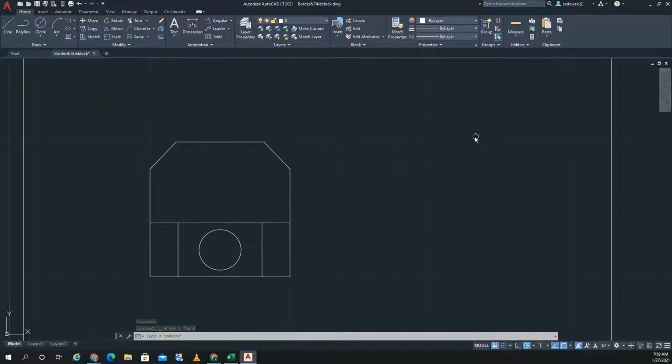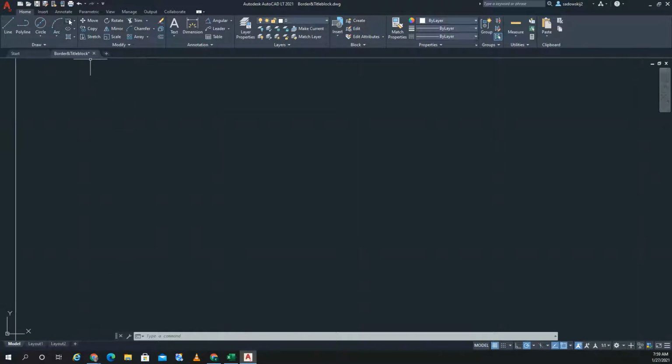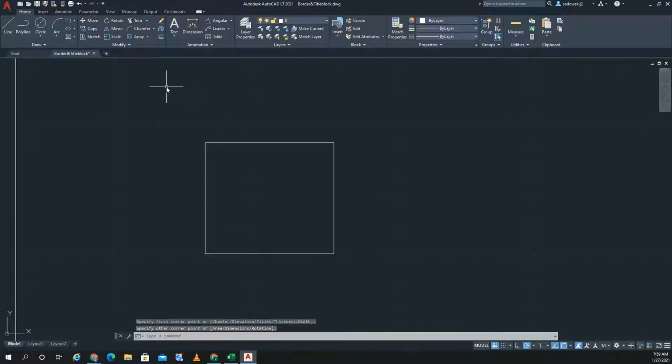There is another way. Let me go over here. There's always another way, right? To do those things. Let me explode this. Okay, so there is another way under here. Under your fillet, you know how to use fillet, there's chamfer. And what you want is you want to then select angle. And you can select 0.5 and then 47 degrees. And what you do is select this, that, and it puts the angle in for you. Okay, good. You select that. Puts the angle in for you.